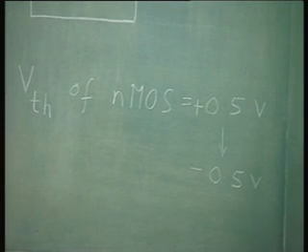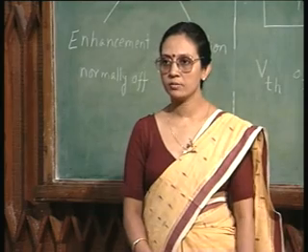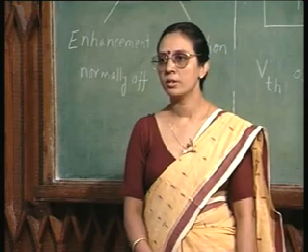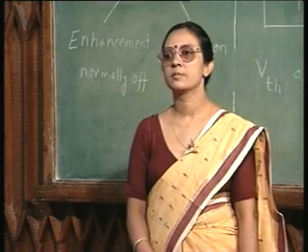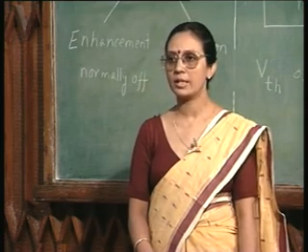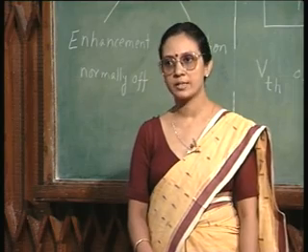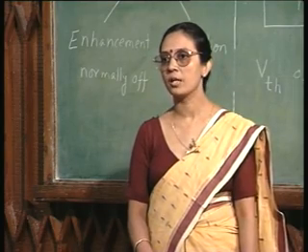If you have pushed it by 1 volt towards the negative direction, what do you have? You opted for an enhancement mode type device. You have now got a MOSFET with a negative threshold voltage. That means it has become a depletion type device. All your circuit goes haywire.